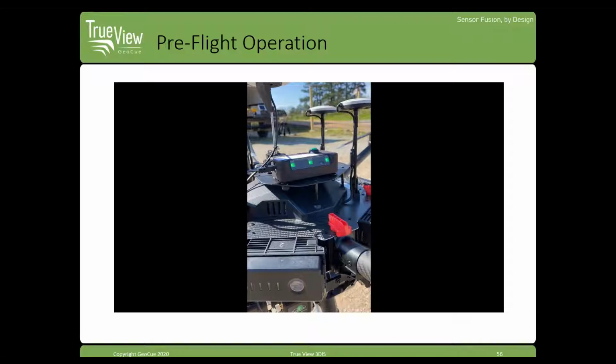If you're not in proximity mode, what you'll do is you'll get a solid yellow light, noting that it's ready to record. It should say on the control box as well. All you have to do is click that cycle button and it'll turn solid green and say it's recording. That's only if you have it not in proximity mode. If you have it in proximity mode, you're just good to fly right now and good to take it up.